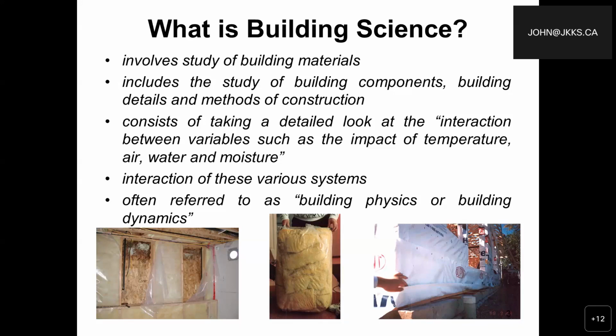In the middle is me holding a baggie full of insulation that was used as an attic access cover. So it's basically a sheet of drywall with a vapor barrier with a whole bunch of that insulation stuffed into it. And what's really hard to see, because I would really have to blow this up, is a lot of condensation, moisture, water inside of that baggie.